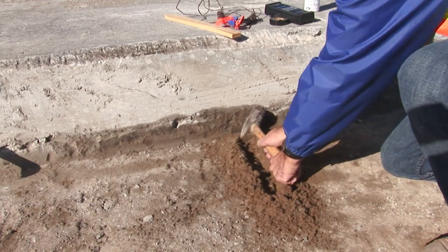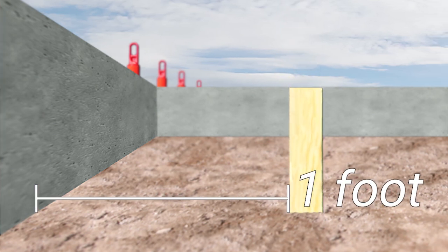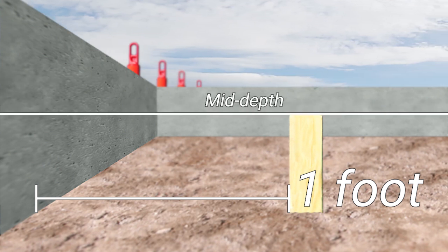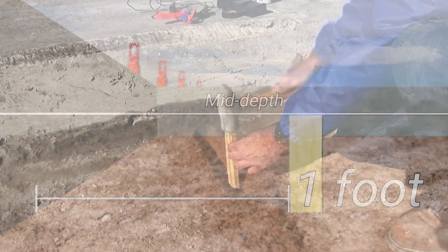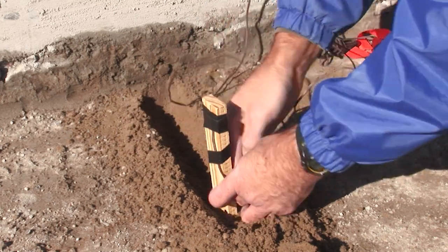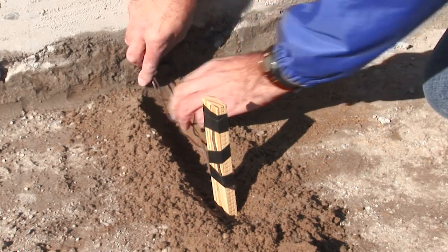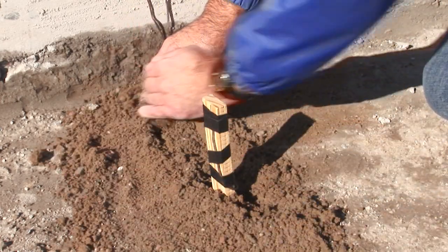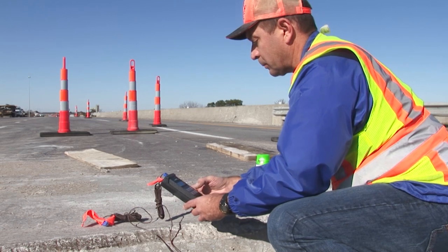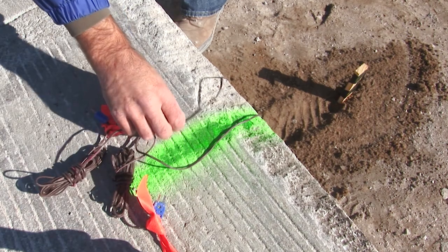To install thermocouple wires where steel bars do not exist, you should place a stake or rod at a minimum of 1 foot from the edge of the existing slab and at approximately mid-depth for the concrete slab placement. Next, attach the thermocouple wires by taping them to the stake or rod. Protect the wires when possible by burying them in the subgrade and run the remaining wire onto the adjacent slab. Test your wire connectors for conductivity and take the necessary steps to protect the wire from being disturbed, as shown previously.